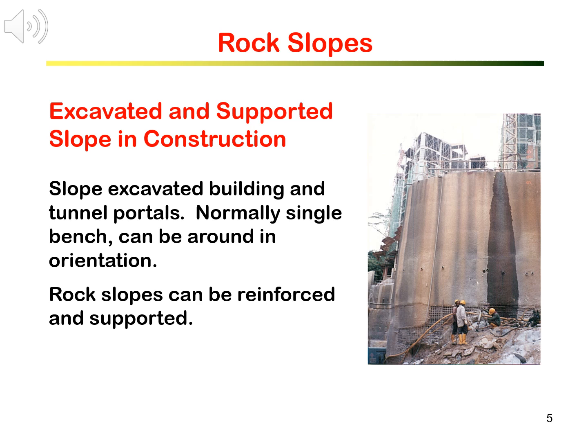Slopes, particularly engineered slopes, if they are potentially unstable and risky, then they are supported or reinforced to ensure the slopes are safe. The slope in this photo is reinforced by steel bolts and supported by concrete.